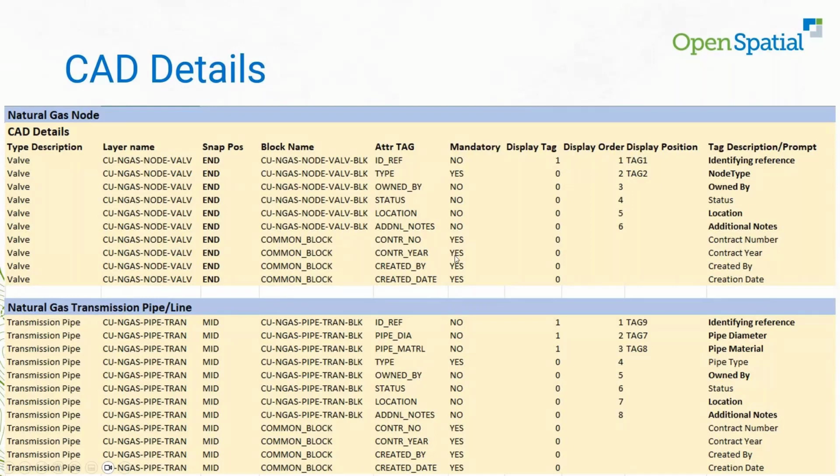We actually then automatically set up the block so that you can set whether you want to display that tag or not. You'll see this one's got 3. So what actually shows automatically there, and even the position of where that tag is, we code certain positions. If it's a point, usually it's sort of the upper left. If it's a line block, you typically have something which is a combination of diameter and material, which is going to be above the block and something below. So that's what these tag positions mean, and descriptions.